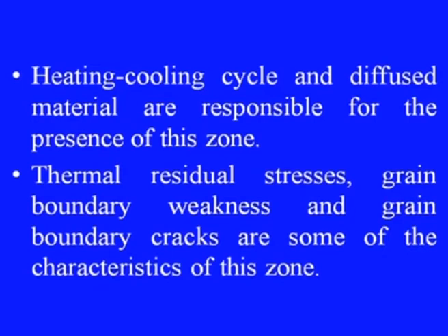Thermal residual stresses, grain boundary weakness and grain boundary cracks are some of the characteristics of this zone. Thus, what we have seen is that almost all the effects present in this heat affected zone are not good for a good work surface or job surface. Therefore, it is to be seen how this heat affected zone can be minimized during this process.